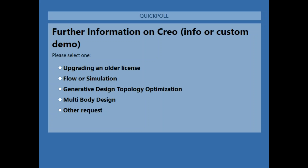One of the questions that came in was, can you base the optimization on multiple loading conditions or criteria? For example, a vertical load separately from a side load, or a stress limit and a displacement limit at the same time. Yeah, so you can lay out, and I'm assuming this is in the context of Creo Simulation Live, but that is something you can do. You can lay out different load sets.